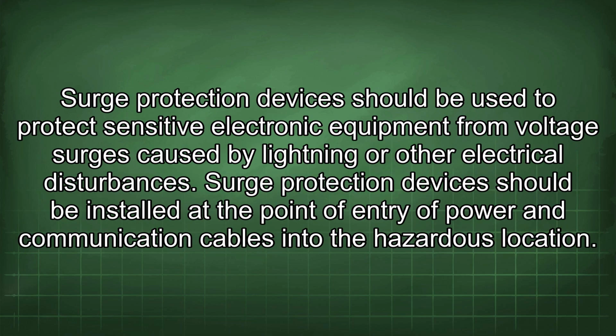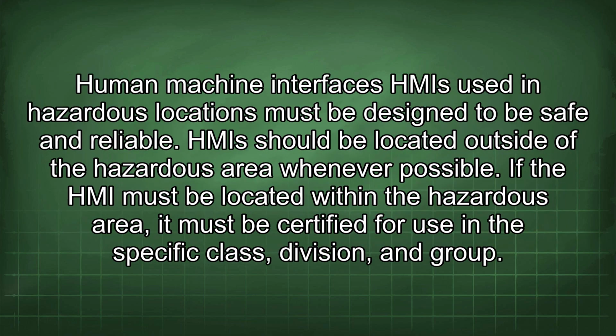Surge protection devices should be used to protect sensitive electronic equipment from voltage surges caused by lightning or other electrical disturbances. Surge protection devices should be installed at the point of entry of power and communication cables into the hazardous location.